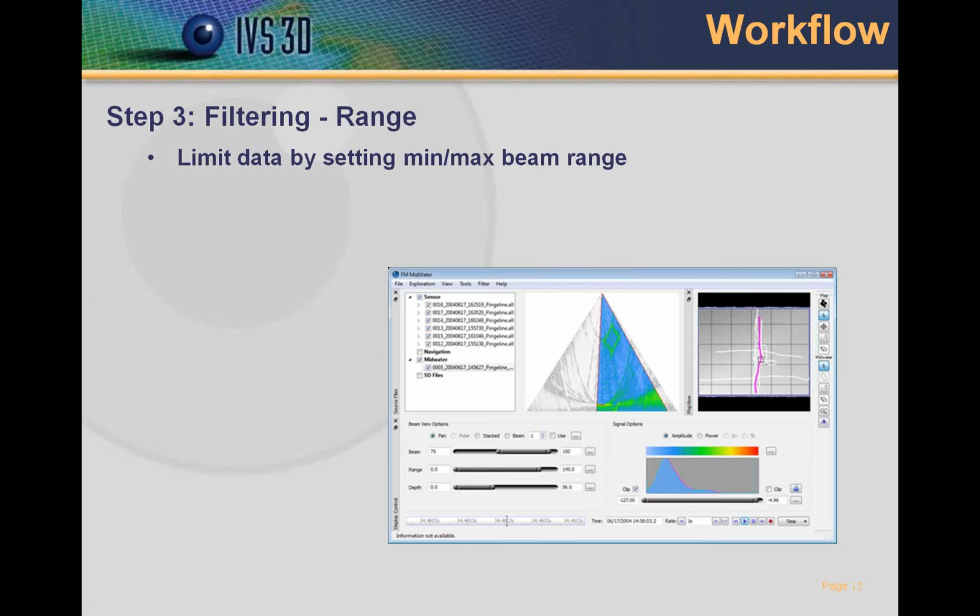The next filter here is range filtering. A lot of times in the water column you'll get near noise, near-transducer noise, bubbles, wake bubbles, that kind of thing. Also at the far range you'll typically get a good side lobe return, and that's another bit that you will want to eliminate for your export. So all of that ends up going away.